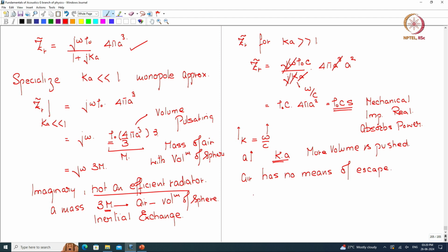What do I mean by that? If I have a piston that is oscillating back and forth, and there is no baffle around it, when this piston tries to push the air in front, and somebody is standing here, this is the ear, the forward movement pushing the air, compressing the air, the air will escape to the back side of the piston because there is no wall.